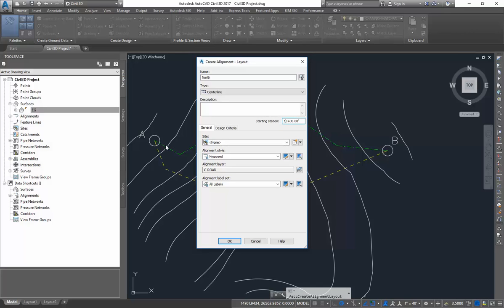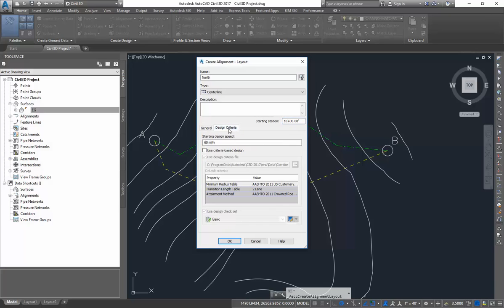And so remembering that we had about 10,000 feet between the 2 points, you'd want to add at least 10,000. So maybe you'd use 10 and 100 for the other one, but it makes it a lot easier to figure out what you're looking at when your drawing gets more and more complicated, that you have these different station conventions.